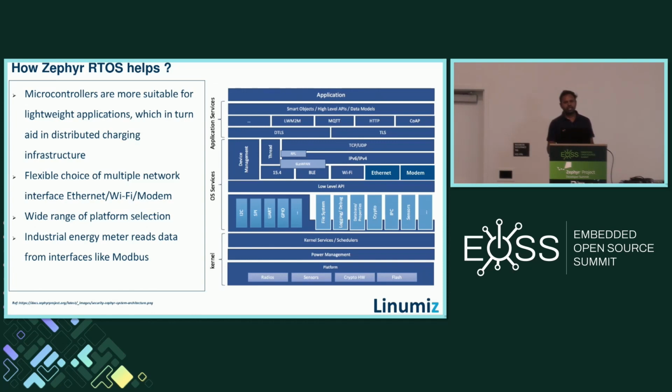Zephyr RTOS has advantages, like a native implementation of the TCP/IP stack, which can be used directly with the Ethernet controller. Apart from that, we can use Wi-Fi controllers, and a lot of Wi-Fi controllers support offloading, which means we can send the payload, and the TCP or IP packet will be framed by the offloading controller. So we have support in Zephyr RTOS for the offloaded socket option also, which reduces the burden on the microcontroller, which can focus on the application side.